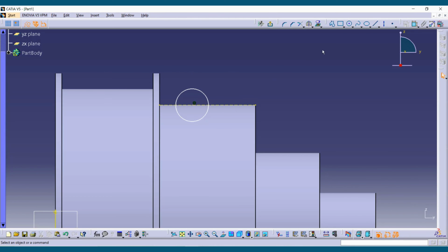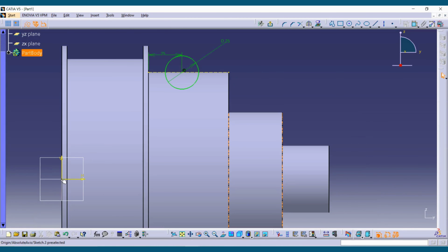Now I'm going to give the dimension from the center reference to the side, for locating this circle as 25 mm. Provide the diameter for the circle, so I'm going to take this diameter here as 25, and now we have this axis here. We just need to say exit and we can go for revolve or groove cut.